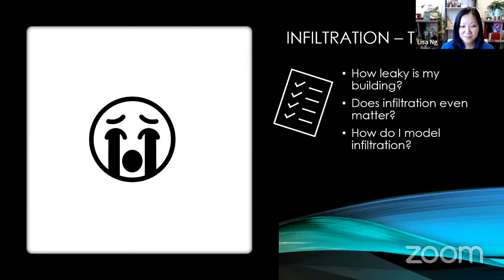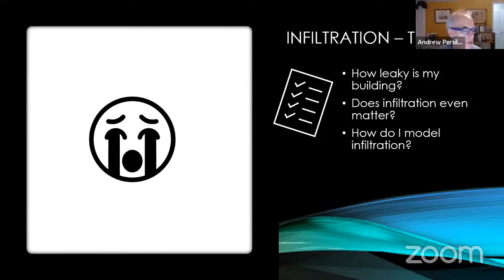I was being somewhat facetious. Divide by 20 is a rule of thumb for residential blower door results. Rules of thumb are great, but if you really want to know what the rate is as a function of weather conditions and all the details, you've got to use models and physics and all that. Rules of thumb are great, but sometimes those thumbs end up in your eye, right?